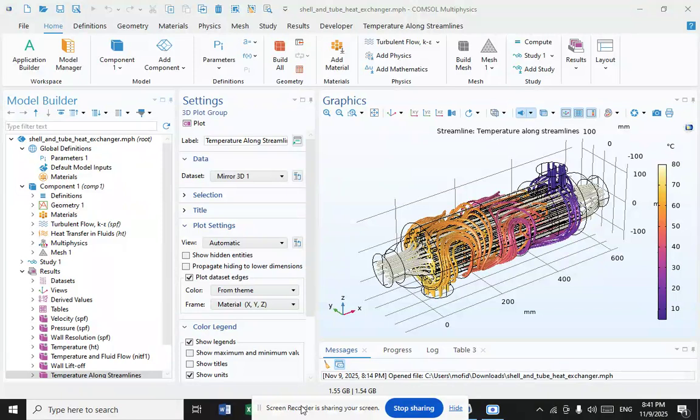The material enables the system to operate at a lower temperature difference and reduce the weight of the equipment. Plate and fin heat exchangers are mostly used for low temperature services such as natural gas, helium, and oxygen liquefaction plants, air separation plants, and transport industries such as motor and aircraft engines.